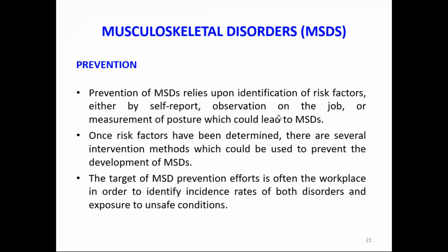Then how to prevent these types of risk? Prevention of MSDs relies upon the identification of risk factors, either by self-report, observations on the job, or measurement of postures. So sometimes if you complain about back pain or shoulder pain, etc., then on that basis we have to look at these activities, how to change the body gesture or posture, how to change manual handling to mechanical handling or automation, and only then can we prevent these MSDs.